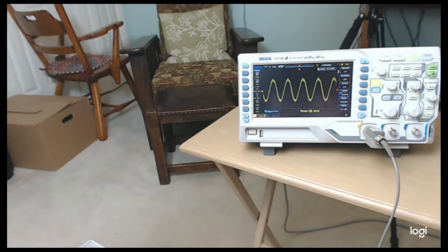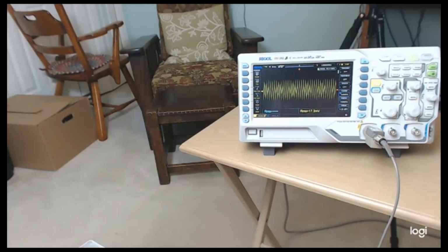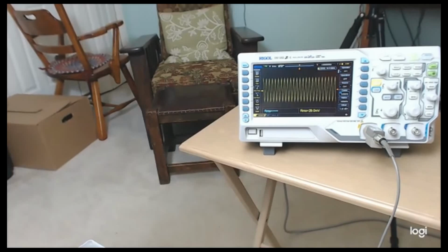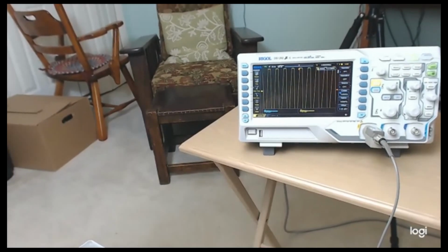It actually does better in the case with all the loose wires and the noise, because now you're starting to pick up noise just from the floppy leads from the setup here. But that's at 40 megahertz, 45, and then it's kind of a mess now. That's at 58. So anyway, it's probably really useful up to about 40 megahertz, and then it starts to kind of drop off. And you might be able to improve it, but I haven't spent any time on that because I'm mostly interested in HF.